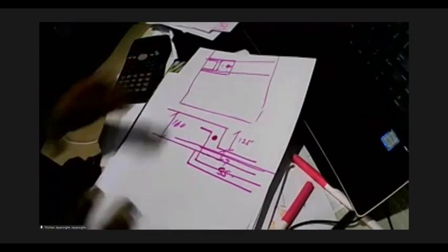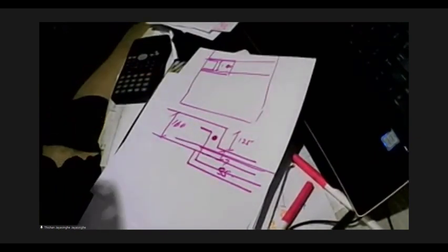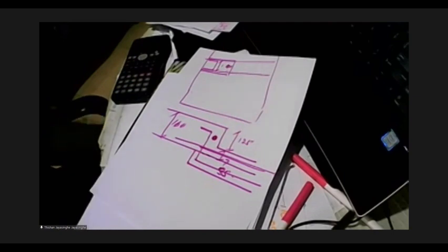So when you have small openings in PT slabs, you can do this type of arrangement. It will not affect the behavior very much. Locally, you can have drops and then facilitate the drops needed in bathrooms. Is that clear, Vashita?